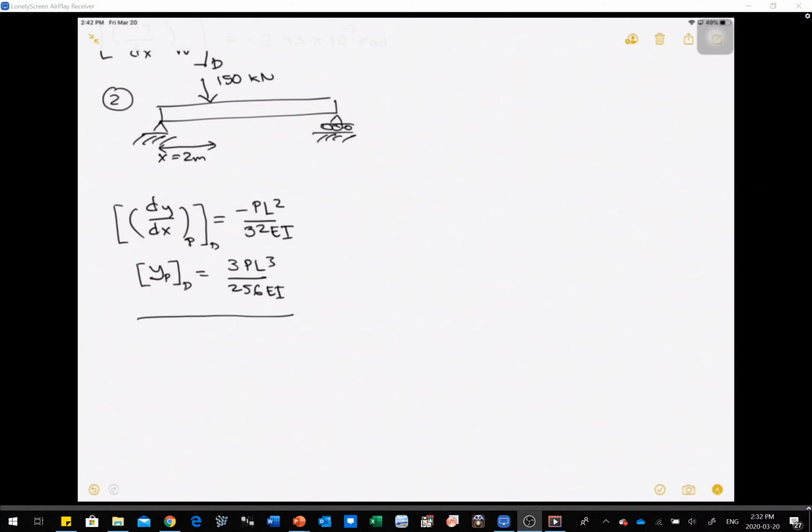Because if we think about the second order differential equation, what we could do is cut our beam right here, and then we have a moment function, or we can cut our beam at this specific point, which has a different moment because we are excluding and including this concentrated load when we calculate M as a function of x.